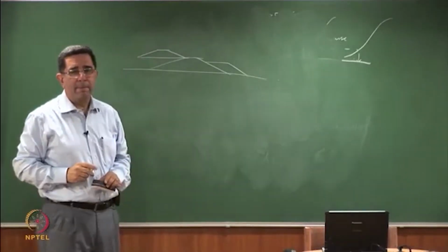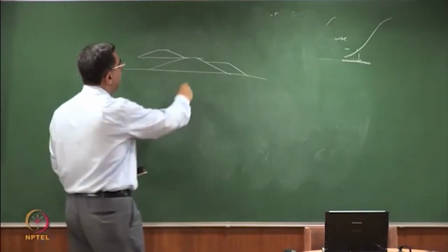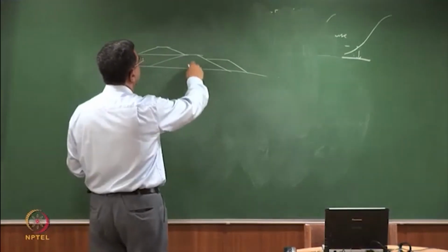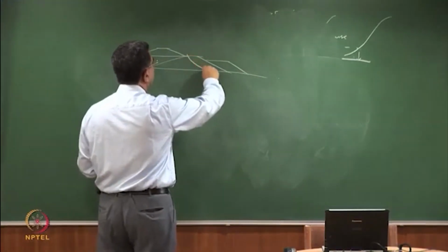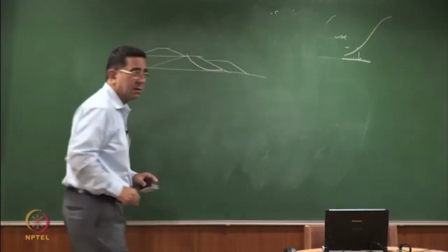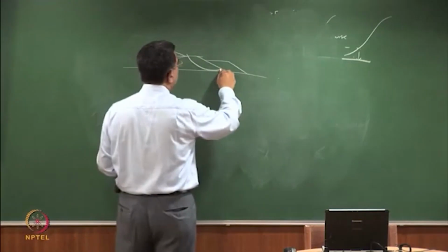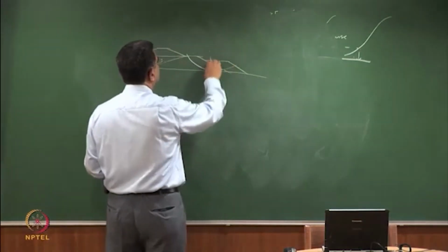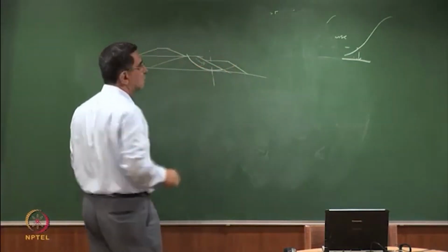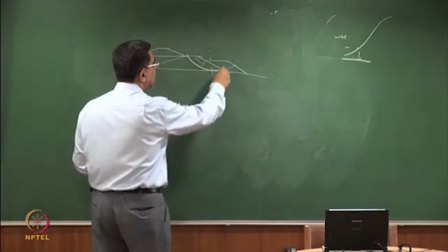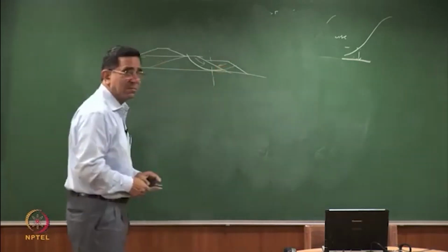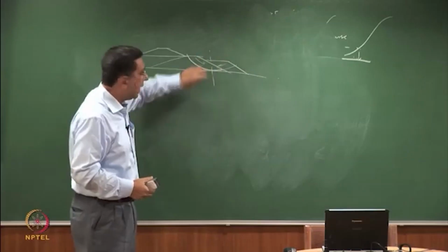Sir, if I consider the slip circle, which was considered earlier without that stabilizing berm, earlier slip surface may be like that. Now weight of the soil, but now if you look at it, it's like this. So please understand, this is the weight of the soil which is pushing it downwards, and this is the weight of the soil which is resisting. So the weight of this soil is adding to the resistance.